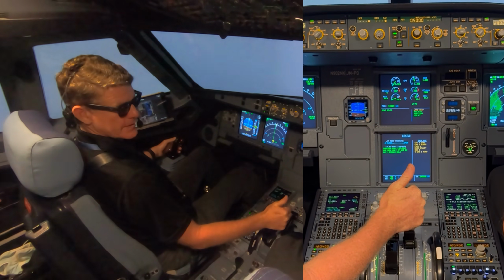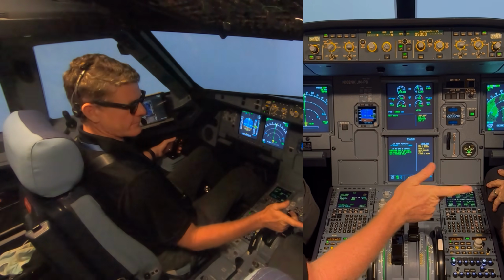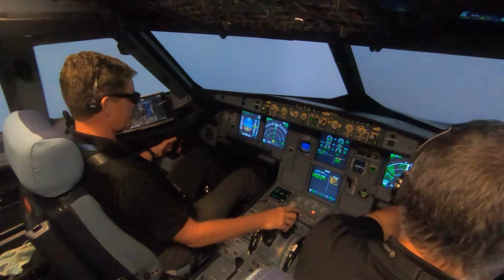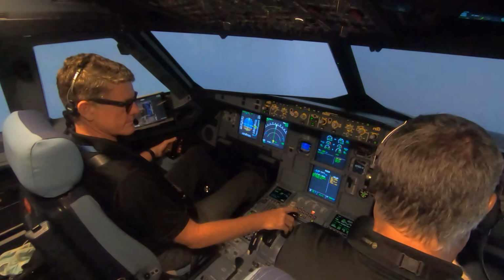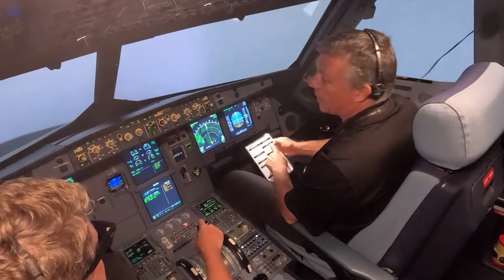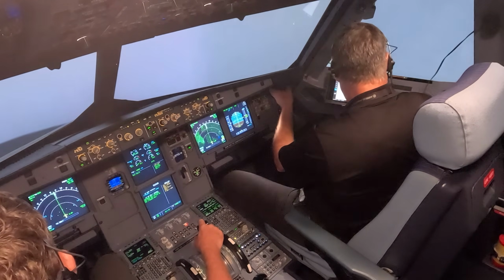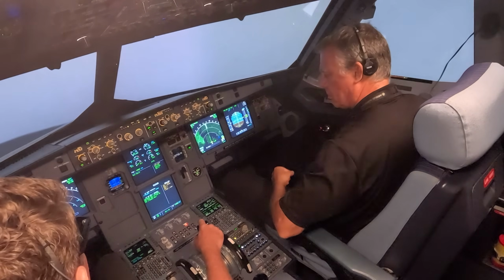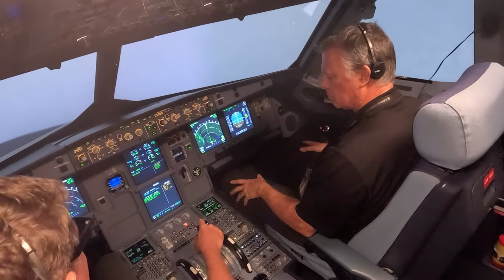After takeoff flow has been accomplished. All done. After takeoff checklist. So it's all done, however we've got the APU running. Copy, thanks. After takeoff checklist is complete. There's no system reset here. Nope. Let's attempt an engine relight.